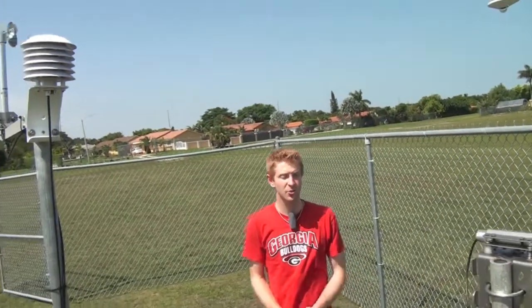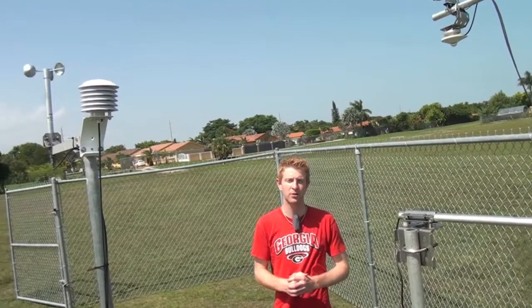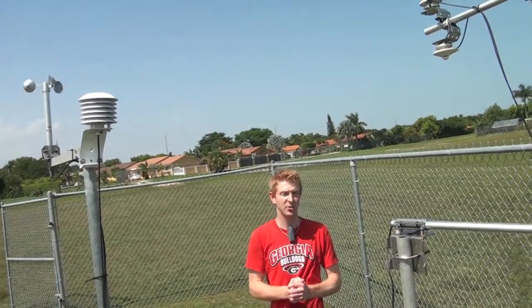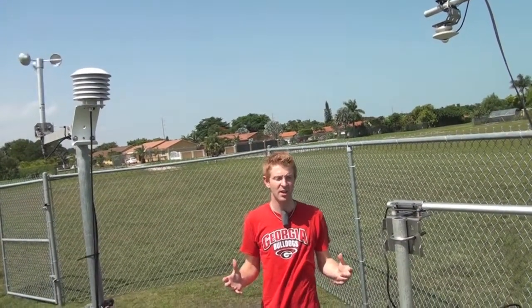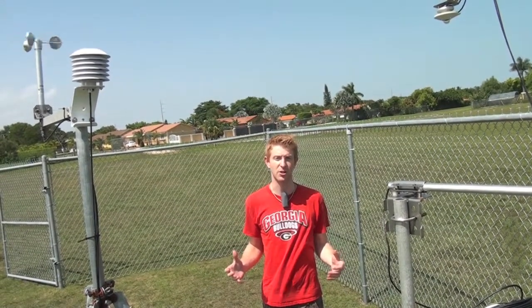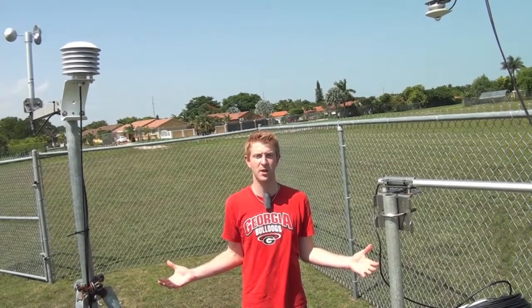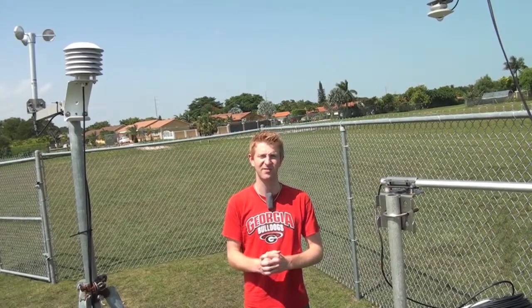First of all, trying to use all of this available data here at the UF site to recreate the Bowen ratio vertical flux equation. Second of all, I used all of this available data to try and use curve fitting software to come up with a Bowen ratio model that would predict the ratio. And third, I used the eddy covariance system data to try and estimate the Bowen ratio on a monthly basis, to use the Bowen ratio energy balance equation to estimate ET.